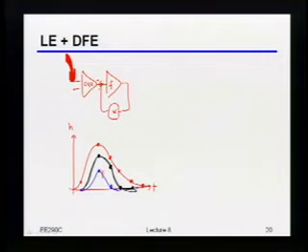But the trick is that crosstalk usually is at a fairly high frequency, right? Because it's usually capacitively or inductively coupled, right? So just by me being able to back off on the bandwidth of the CTLE, I'll just be filtering the crosstalk more heavily, right? It's not that it's going to go away, but at least I won't be amplifying it as much as I was in the past.